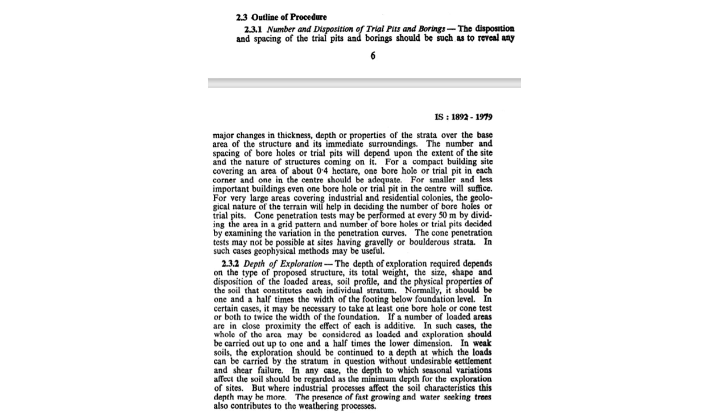Whereas for borings, you will have different types of instruments, because in borings you are going vertically, you need to evaluate the subsoil profile, and technically it should go up to the bedrock, okay, or the hard stratum that exists. So for borings, depending upon the type of soil, you have different types of boring instruments and techniques which are to be followed. Okay, so trial pits are something like open excavation. It's a small pit which goes up to only a minimum depth of 2 meter or 3 meter.